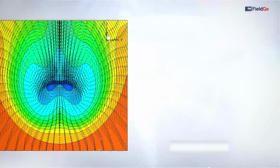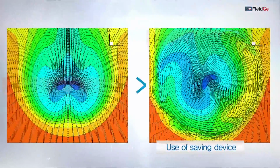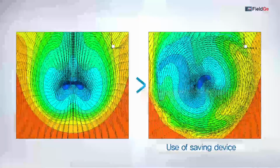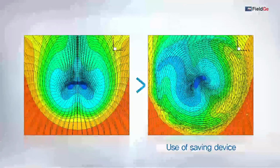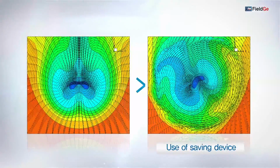One can observe a change in the speed vector at the propeller plane. The device is mounted on the starboard side of the duct. This duct combines a wake equalizing duct with a pre-swirl plate on the starboard side of the duct. The effectiveness may depend on local flow details like the strength and position of the bilge vortex.